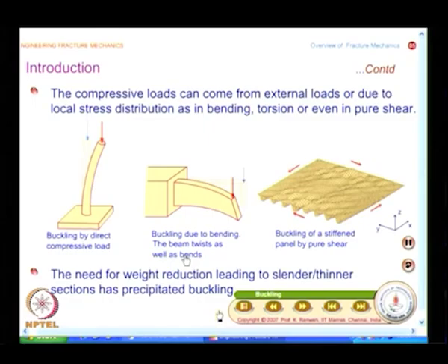So, when you are really looking at a structure in the larger perspective, you will have to define what a failure is, and that failure should be addressed. So, do not think there is always material separation. Material separation is one of the aspects. Buckling could be equally a challenging problem that you may have to deal with for the kind of design scenario you are involved with. So, you have to define what a failure is, and this is what you learn in a first level course. You will learn yielding should be avoided, and you also learn buckling should be avoided.